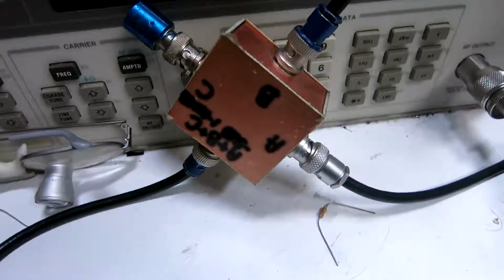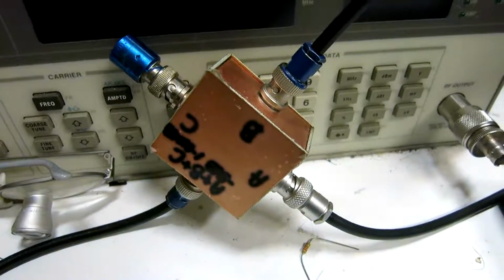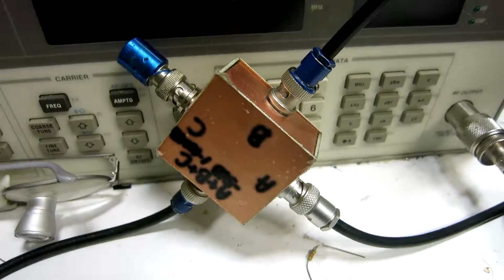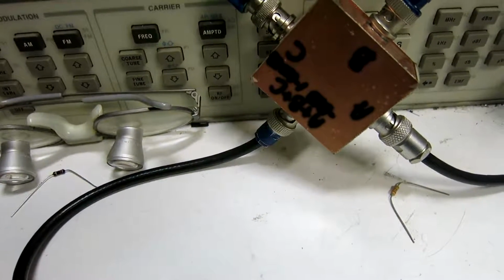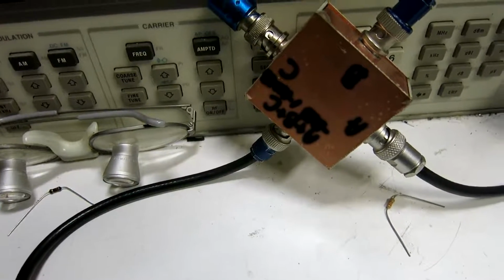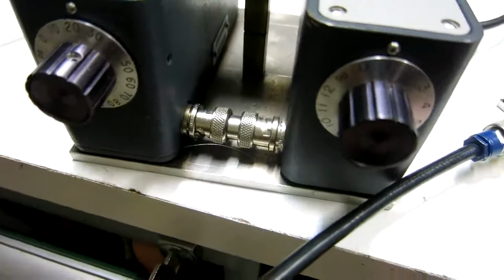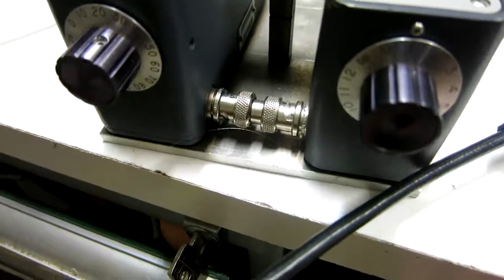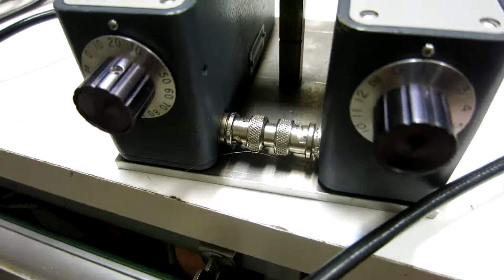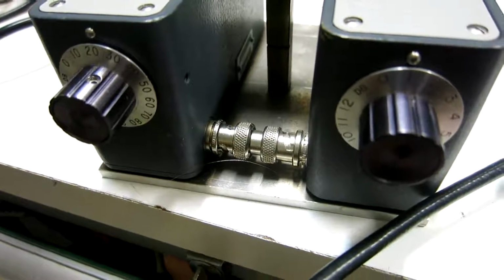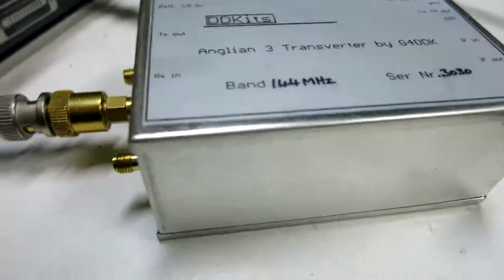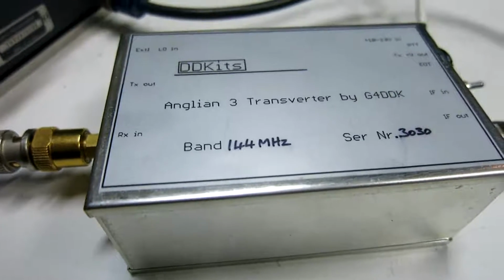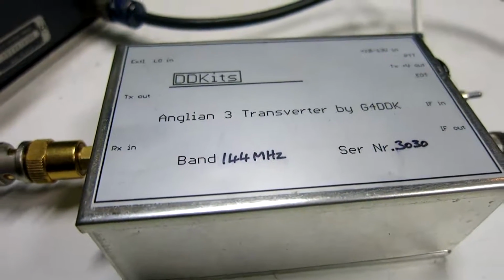They are combined in a hybrid, a 3-port hybrid, where the third port just has a dummy load. The output here is attenuated by 5 dB. That's a factor of 3. And then it goes through these attenuators, which are set to 21 dB. Means minus 26 dBm into this box, which means that the peak power is minus 20 dBm.